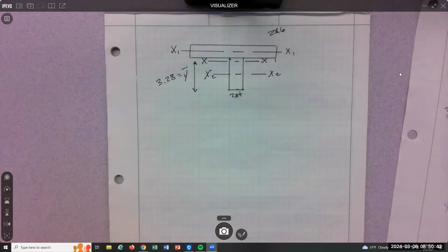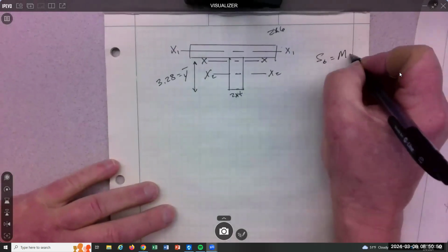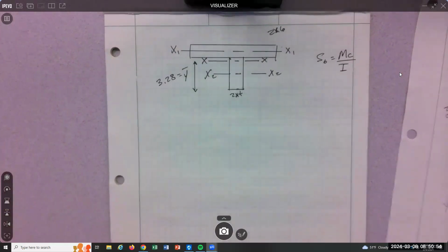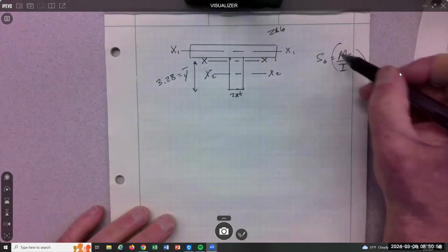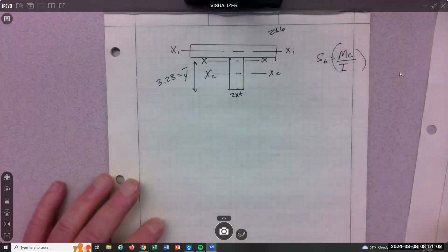If we then wanted the inertia, the area moment of inertia, and the reason we do, remember, is bending stress is Mc over I. So if this is the shape that we're gonna load in bending, then this is the equation we're gonna run to find bending stress. We're gonna find the moment, that'll be a statics thing.